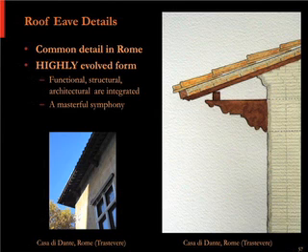And the very last point is, if you look at the watercolor at the right, notice the main supporting member, and then the rafters overhang that, coming down the slope. And then the wood stop at the end overhangs that. And then the tile overhangs that. So everything is overhanging everything else to kind of shelter that.